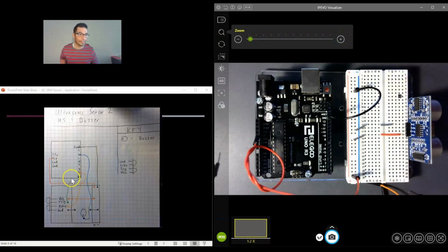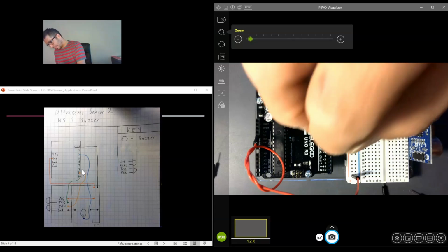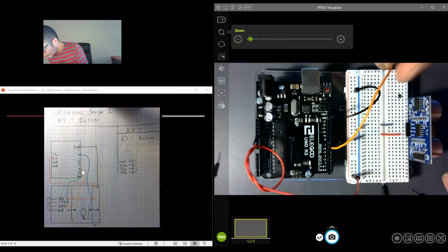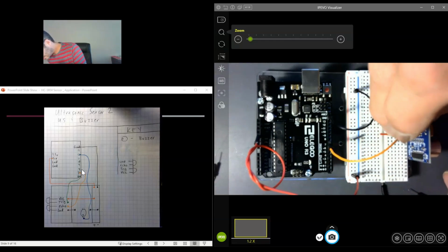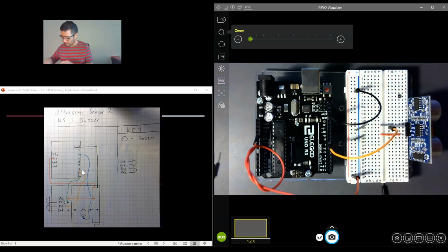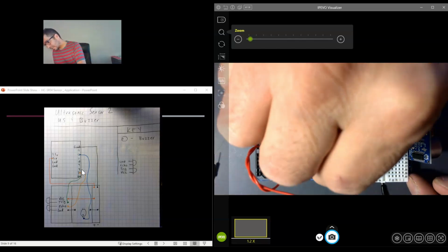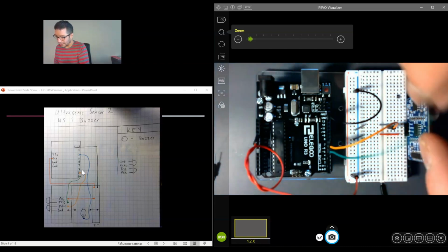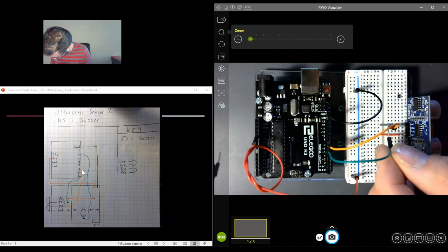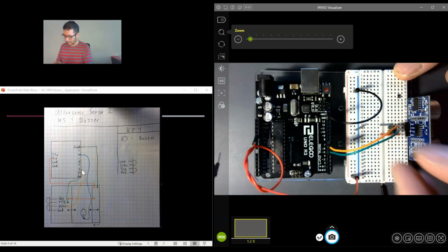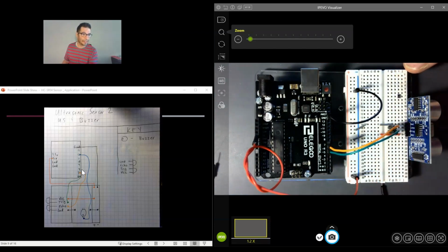All right. It looks like we have echo and trigger going to 7. Here, and echo is orange. So I'm going to plug into pin 7 to echo. Trigger is pin 6, and that's going to green. Echo 7, trigger 6, okay, yep.